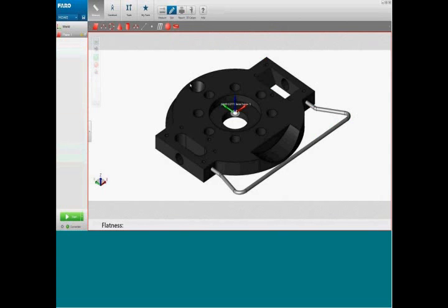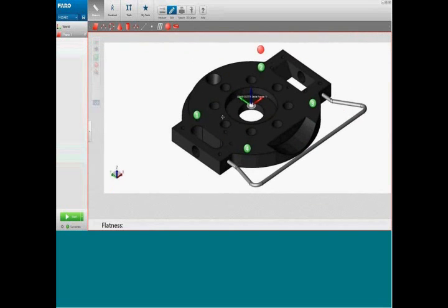Once the image is imported, we have other options available within the side menu. Using the green dot, we can simply click on the component to determine where the user must probe, and also the number of points. We can then use the red to detail where to compensate. The slide bar below the points will increase or decrease the size of the points. We then have a pan where we can simply move around, and we can also zoom in using the roller ball on the mouse.